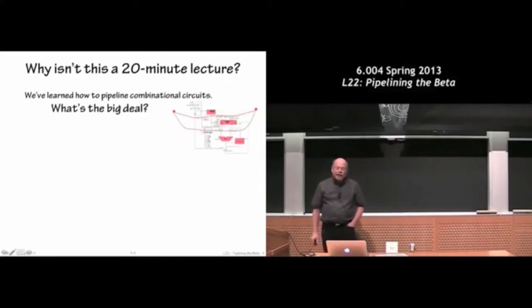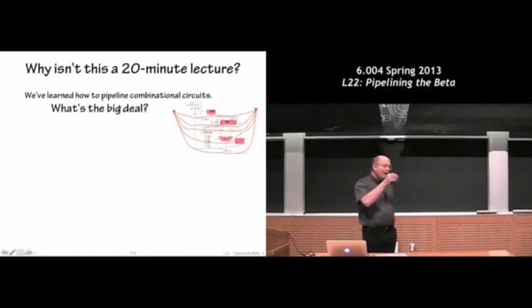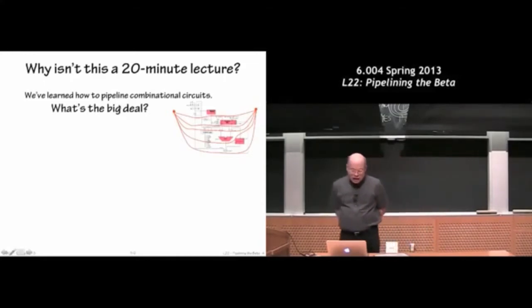We pipeline it. We take all those slow blocks, all the washing machines and dryers, and we put them into separate pipeline stages. And for a particularly slow block, we might choose to interleave them, right? We could say, oh, fine, we'll make 2 ALUs and run them sort of half a cycle off from each other. And we could use our interleaving strategies to make things as fast as we want.